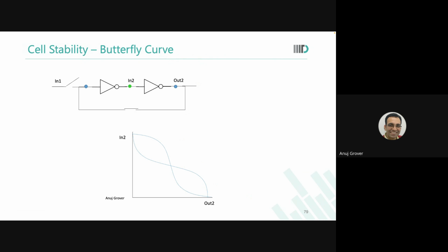And then there is this one definition of static noise margin, linked to the butterfly curves. How many of you watched the videos? So all of you would know. What is that one definition of static noise margin dependent on the butterfly curves? When we make a square in the smaller lobe, the side width of that square is lower.